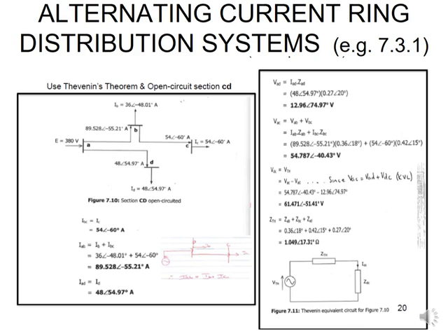Then we go and look now at IAB, which is the first part of that top section. If you're looking at where your node B point is, and I've drawn it nicely here on the side for you, your IAB splits up into IB and IBC, remembering that IBC is the same as IC. Check how I've drawn it so that you can even see your IBC being the same as IC. So it simply means that your IAB is going to be equal to your IB plus your IBC, which is the same as your IC. You put those two together and you get that 89.5.